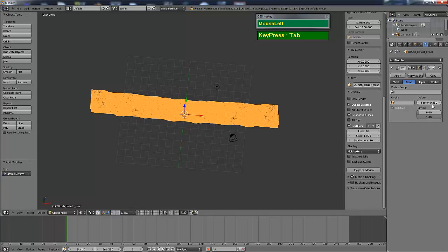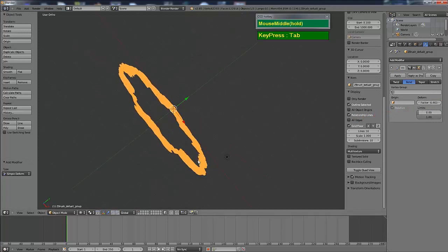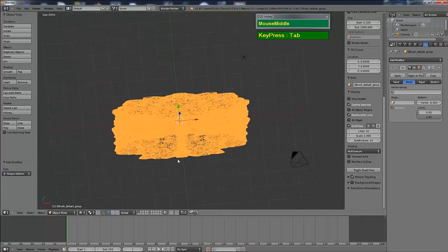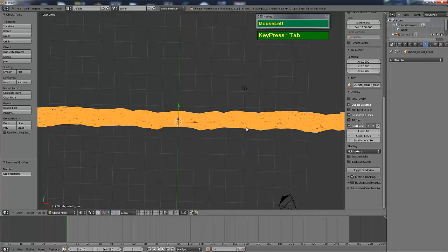Okay, so I'm going to apply a value, because I know my normals are pointing this way. If you notice, although I applied a deform, the mesh seems to be squashed. The reason is very simple: I did not freeze the scale. So let me just get rid of this modifier for now.